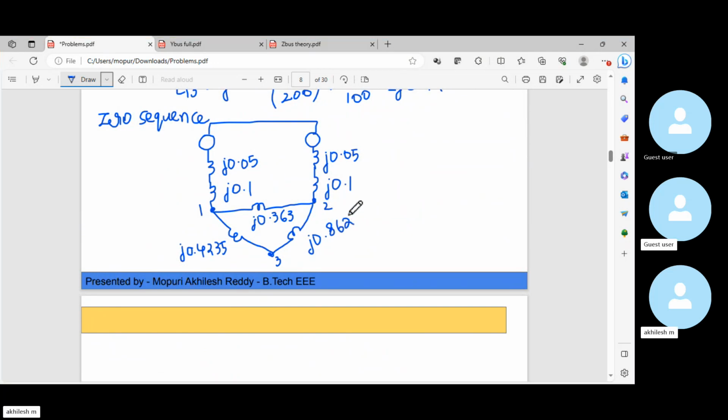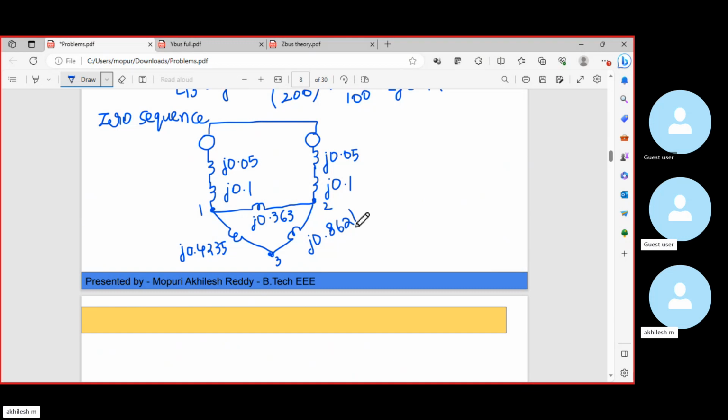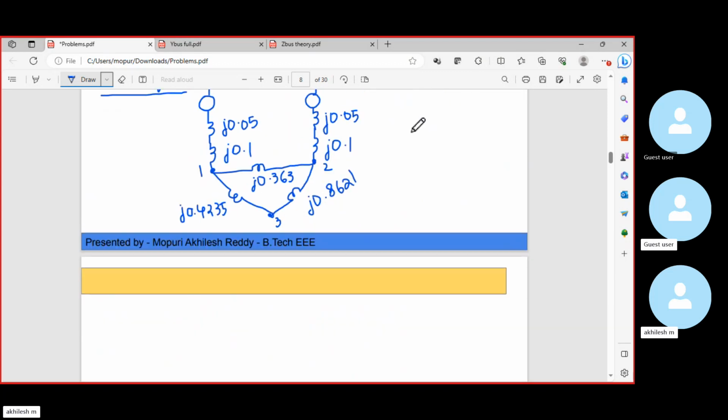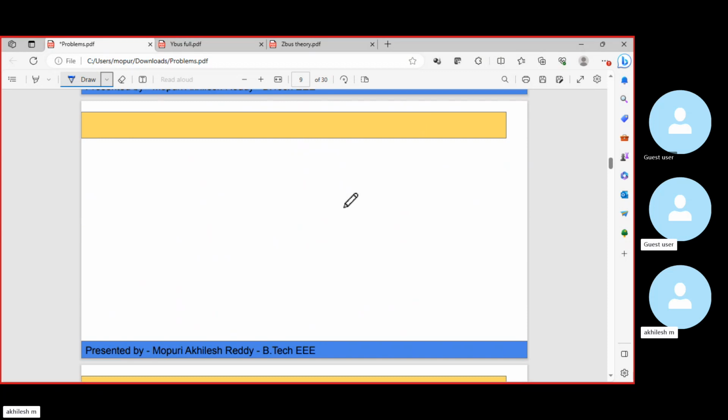Now, in the previous discussion, we have seen that whenever we are using Thevenin's method for finding Z effective or XTH, we need to convert that circuit into two parallel branches. Let us recap. We convert the circuit into a circuit with the pre-fault voltage and the fault impedance ZF, and then two parallel branches.